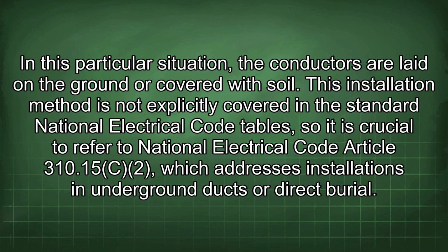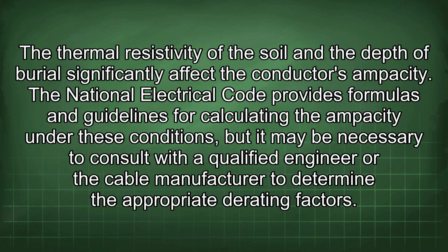In this particular situation, the conductors are laid on the ground or covered with soil. This installation method is not explicitly covered in the standard National Electrical Code tables, so it is crucial to refer to National Electrical Code Article 310.15(C)(2), which addresses installations in underground ducts or direct burial. The thermal resistivity of the soil and the depth of burial significantly affect the conductor's ampacity. The National Electrical Code provides formulas and guidelines for calculating the ampacity under these conditions, but it may be necessary to consult with a qualified engineer or the cable manufacturer to determine the appropriate derating factors.